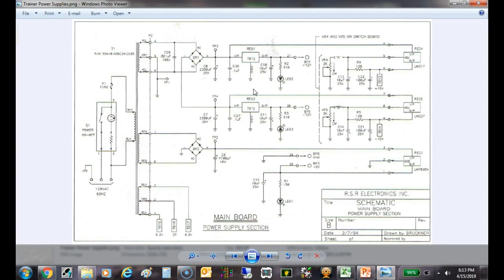There's a little LEDs that come on when you turn your power supply on, right? Here's the 5-volt regulator. It's a big one. It's like a 5-amp regulator. See, there it is right there. There's the what? There's the rectifier. There's the filter, and there's the regulator right there. This is the one that goes out most often right here.